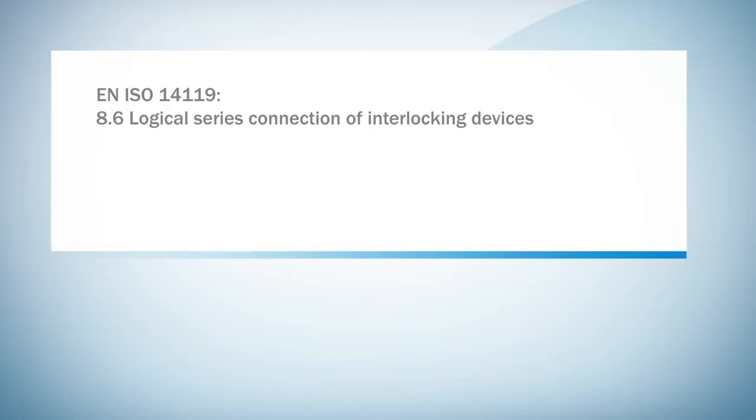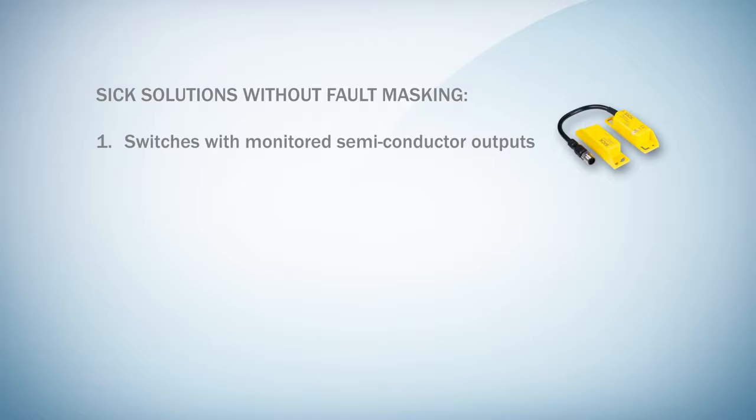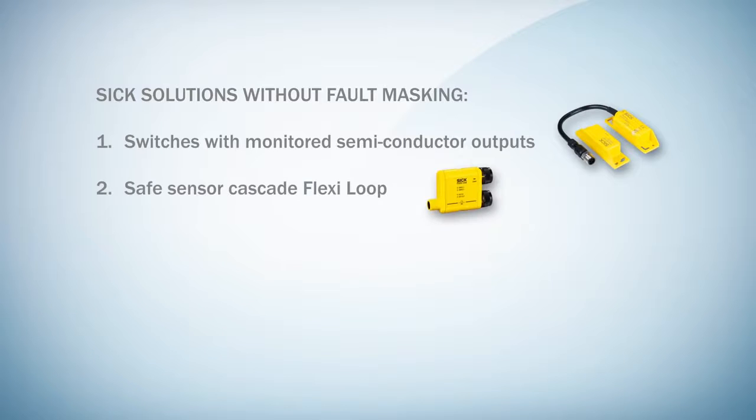Because of this possible danger, the standard for interlocking devices and the forthcoming technical report limit the performance level of cascaded safety switches with volt-free contacts. To avoid this limitation, SICK offers several solutions. First, the switches with monitored semiconductor outputs, and second, the innovative safe sensor cascade FlexiLoop.